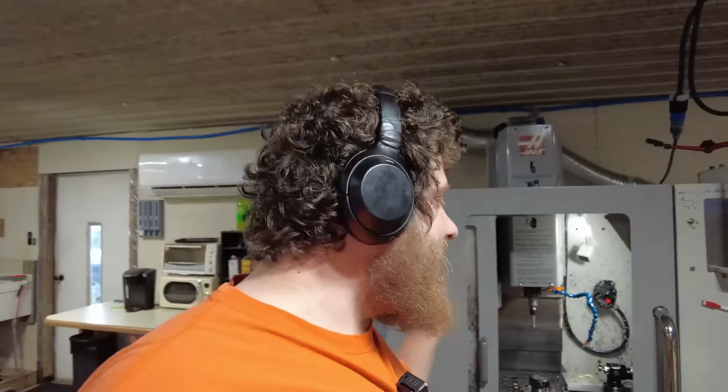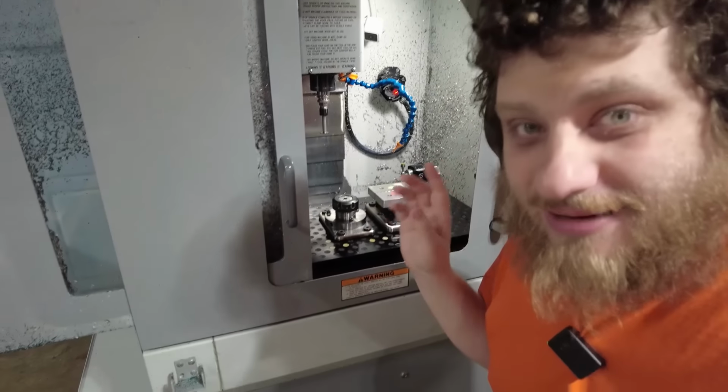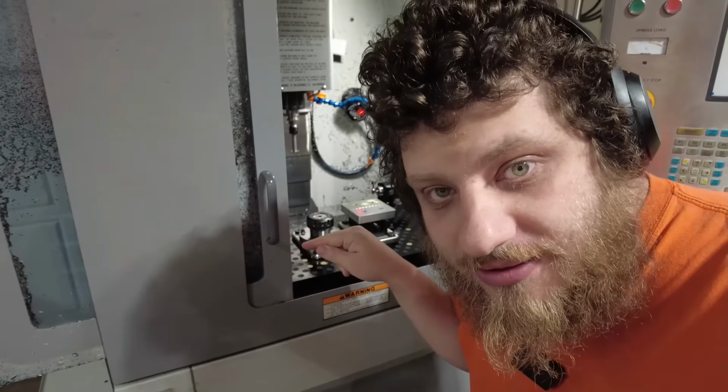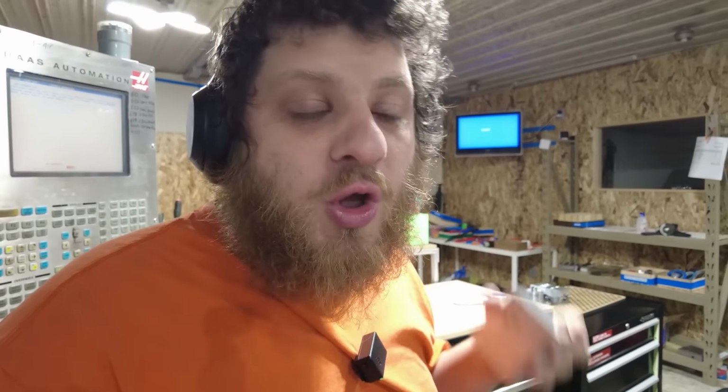If you are trying to do short-term work, what matters is how long it takes your part to get out the door. If your part is waiting on CAM, it is not on the machine getting closer to shipping. But you don't need to have all of your CAM done before you put it on the machine. If you have good processes and proven speeds and feeds, you can throw your part onto the machine and do the bulk of the material removal while you're still finishing the rest of the program.